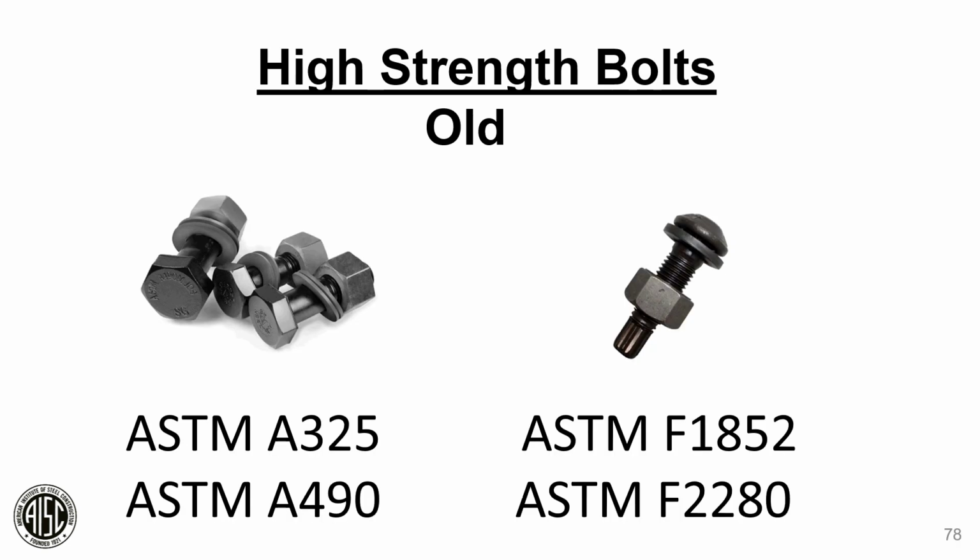So let's talk about bolts. If you notice, this slide is designated as old. For years, and everybody knows, we've specified ASTM A325 and ASTM A490 for hex head bolts. And for tension control bolts, we specified ASTM F1852 and F2280. Well, that was common up until 2015.